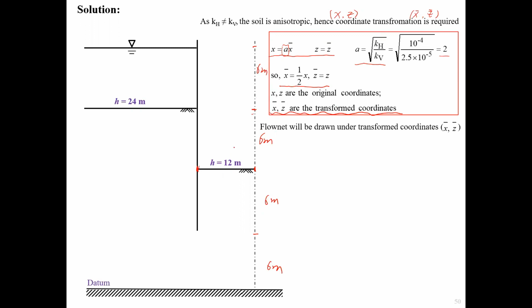So now you should know very clearly why we get the value 24 here, right? It's uw divided by gamma w plus z. So what's the pressure height value for this level, if the datum is here? 24. It's like 6 with this extra 6. How do we get 24? I try to ask you this because I explained it multiple times before. It will be the sum of the pressure height and the water height. So uw divided by gamma w, that's the water height. What's the water height value?